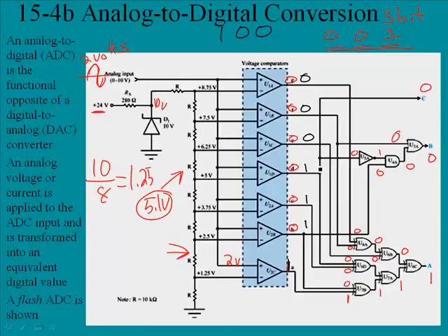We're going to put a 1 here, which will feed over here to C, and that in fact corresponds to our 1 right there. But let's see what happens to B and C. So coming in here, we're going to come into this OR gate, that would be a 1 there, and we have a 1 there, and then from here again we have a 0, and that would be inverted to a 1.